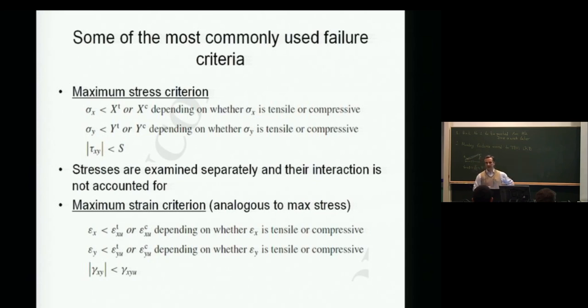Please. The stress that we're looking at here, is it a combination of matrix and the fibers, or only fibers? That's a good question, whether the stress is the combination of matrix and fibers or just individual. It's the ply level stress, which means you have already translated fibers and matrix into a single ply with the stiffness matrix, ABD matrix, and you are calculating the corresponding stresses and strains for the entire ply. It's not on the fiber level or on the matrix level alone.